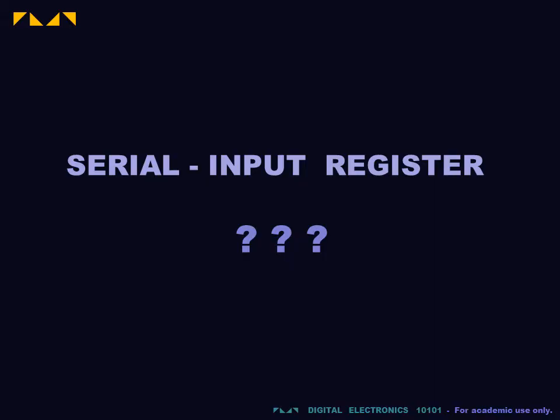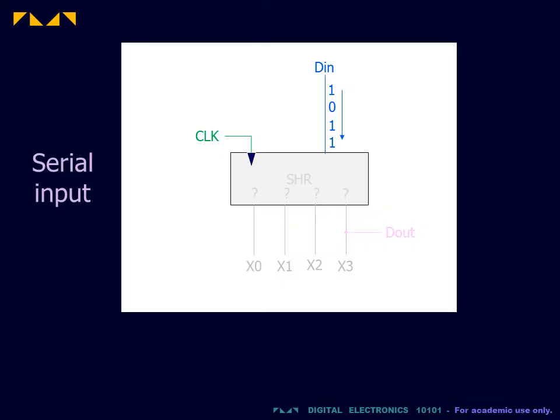We will now explore how to design a serial input register. A register is a multi-bit data storage device. Serial data is latched synchronously as the leftmost bit of the register. With each successive latch, the stored data is shifted from left to right.